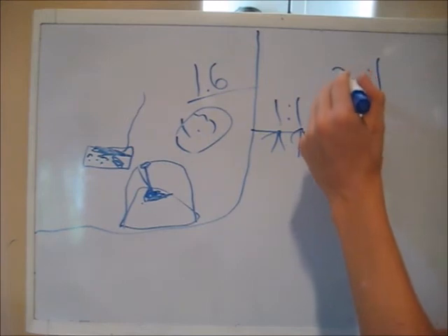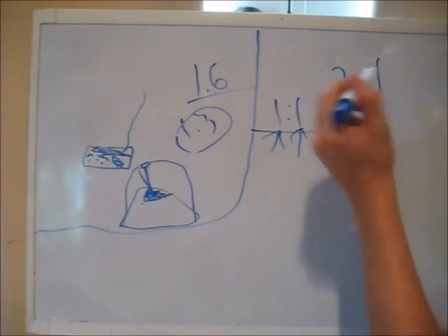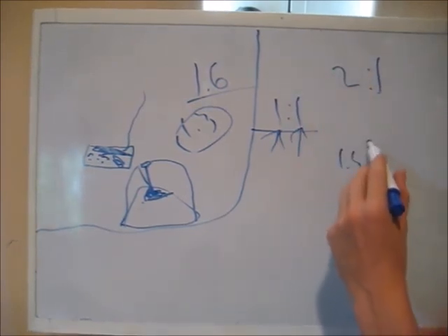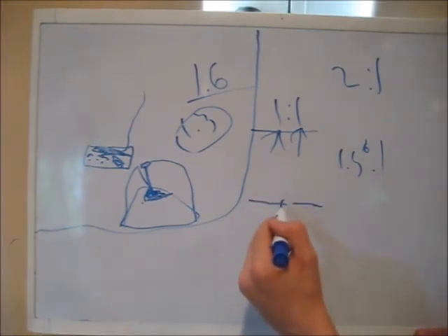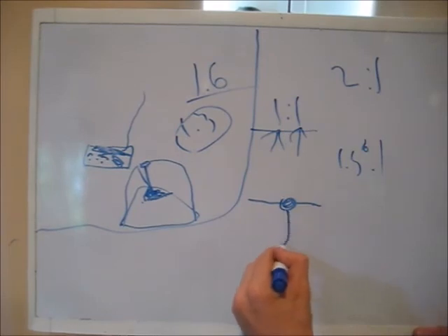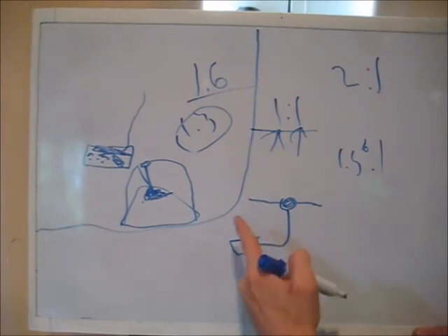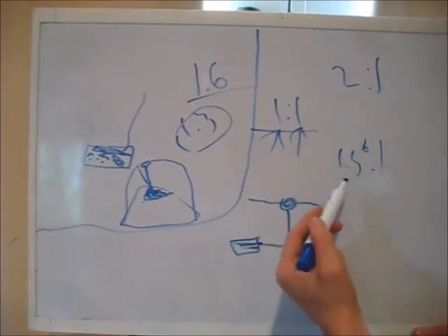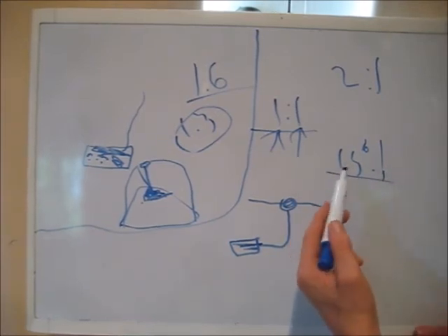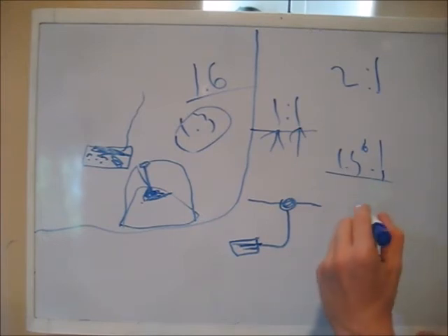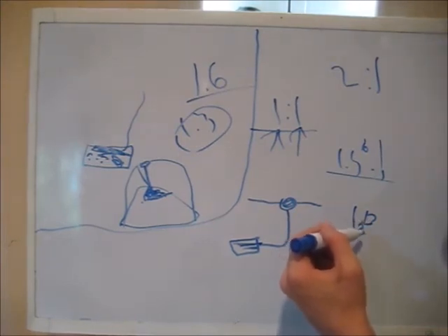If you get a 2:1, that means your antenna is 100 ohms, not 50. That's a 2:1 SWR. A 1.5:1 SWR is 75 ohms. So if you made an antenna that was perfectly resonant for 75 ohms and fed it with 75 ohm coax into the back of your radio, you would have a 1.5:1 SWR. Now, that's okay. 75 ohms going into a 50 ohm radio isn't going to hurt anything as long as you don't operate for an extended period of time. Ideally, you should probably keep it at 60 ohms or less, which is around a 1.3.